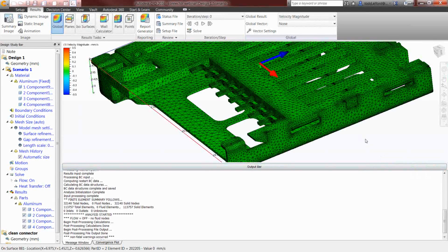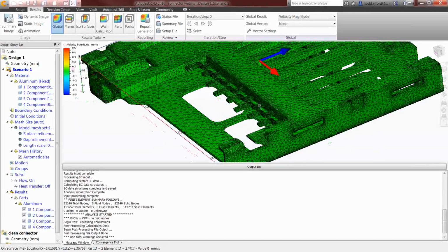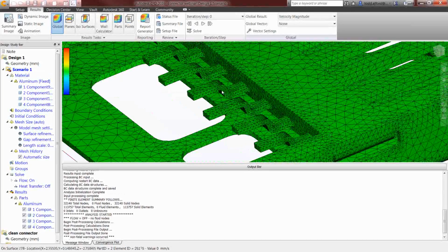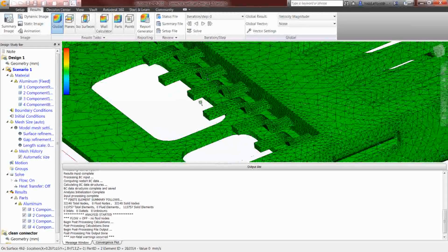Oh, absolutely. That's actually a really good point, because I meant to point that out. Here I'm showing that a model will mesh either way, and even with the small gaps that we had, the mesher will still do it. I've put a fluid around this. I just didn't feel it was completely necessary because it takes a little bit longer to mesh. But when you look at the edge lengths, they're very highly concentrated around these pins, where I deleted some of the curvature.